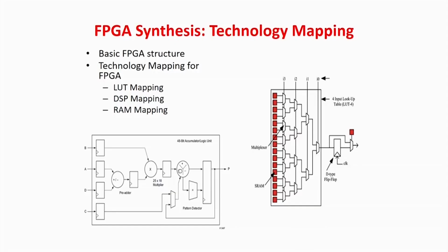Then again nowadays there are a lot of variations, so that either you can fabricate your circuit in ASIC, and nowadays FPGAs are coming up. So now we have very, very large size FPGAs, so even processors can be implemented and validated in FPGAs. So a few modules will be dedicated where we will try to see how you can have an optimized design if you have an FPGA in place, because FPGA is not a gate level block. There are something called LUTs, ready-made blocks like digital signal processing blocks, RAMs, some dedicated blocks are available. So say that I require a multiplier, you need not synthesize the multiplier, multipliers will be available. You have some digital signal processing block, already they are available, so you can directly map it there. Given those fixed blocks, how the other parts can be optimized. That is some technology which is recently coming and not too much discussed in normal CAD for VLSI books.